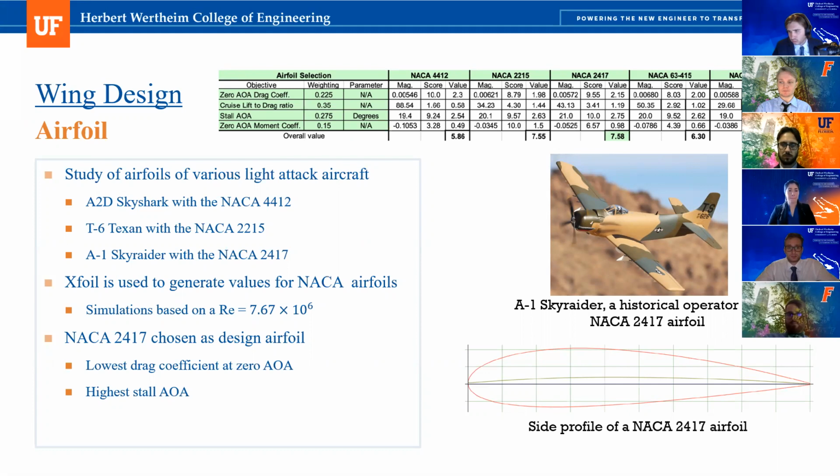What should be the weight? What should be the thrust weight ratio? What is the wing loading? What is the lift drag ratio? We have that initial estimation, and then we use that initial estimation to guide our wing design, tail design, power plant selection, fuselage design, and everything. So it'd be nicer if you, in the presentation from the big picture, have the initial estimation result showing at least in one slide and spend like 10 seconds there, right?